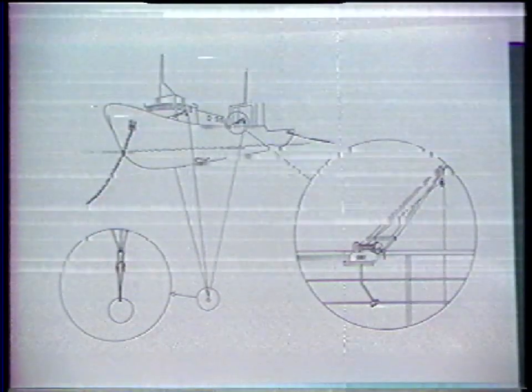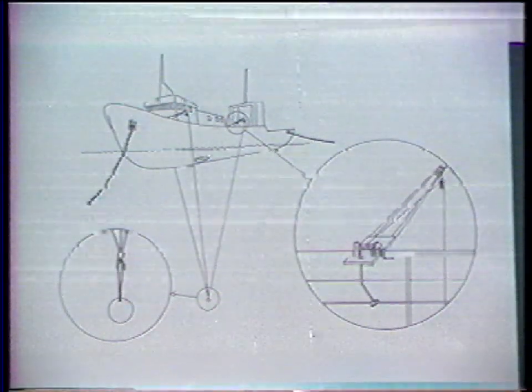Winches to guide and steer lines to the sphere for its centering in the echo sounder beam are affixed to the deck railing. This is done in accordance with the detailed ship drawings. One winch is placed in the transverse plane of the ship running through the transducer. The other 2 winches are placed on the opposite side of the ship, at distances necessary to forming an approximate equilateral triangle to facilitate the sphere alignment process.